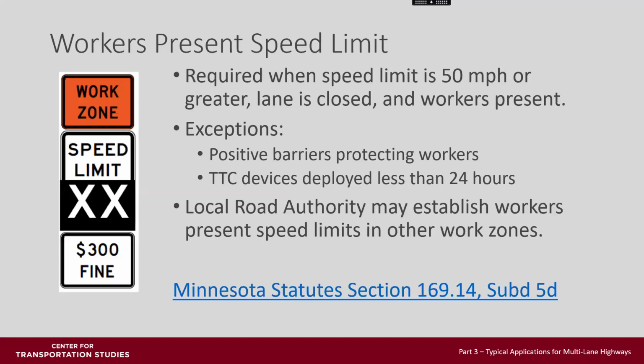The speed limit in work zones when workers are present is contained in Minnesota Statutes 169.14 and allows, or in some cases requires, the governing road authority to authorize the use of reduced maximum speed limits in highway work zones without having to conduct an engineering and traffic investigation.